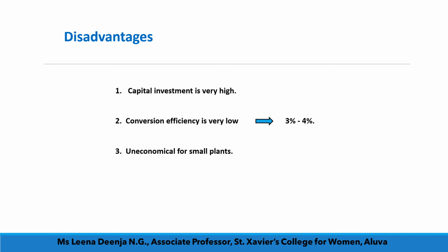The disadvantages are that capital investment is very high. Due to the small temperature difference between surface water and deep water, the conversion efficiency is very low, that is about 3% to 4%. Due to low efficiency, high capital costs and maintenance costs, it is uneconomical for small plants.